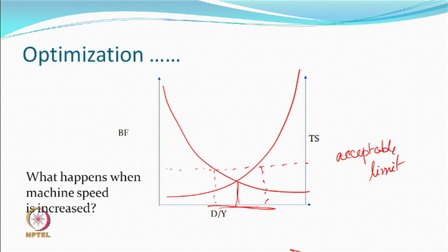That of course is possible, but if you measure tension, which can be measured without measuring crimp rigidity, without measuring broken filament, without measuring tight spots, then you have some correlation which is going to help you to remain in a range. So, if we increase the machine speed, let us say I am running at 600 meters per minute and I want to go to 800 meters per minute and then 1000 meters per minute, I am just changing the speed. What it means is you are changing the residence time.